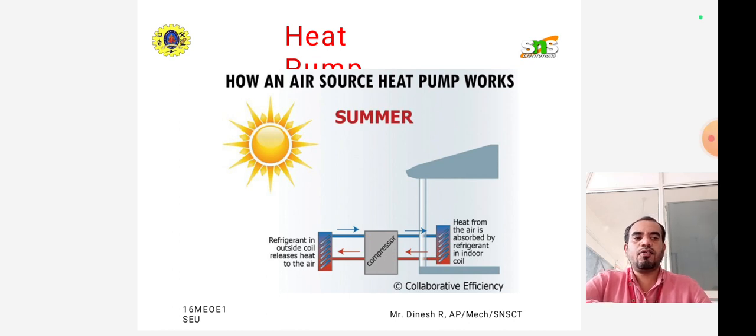This fluid evaporates and expands in the engine before reaching the condenser, where it condenses at low pressure. The condenser is cooled by the water to be pumped. The fluid is then re-injected in the boiler to close the cycle. So basically the working is very easy when compared to others, and by using the solar heat pumping system,